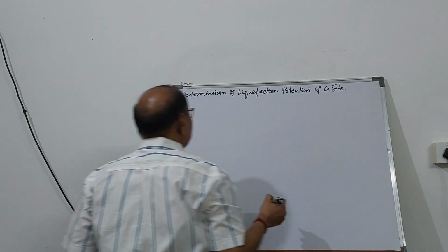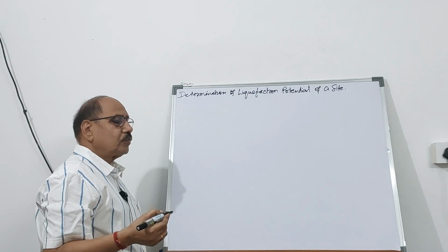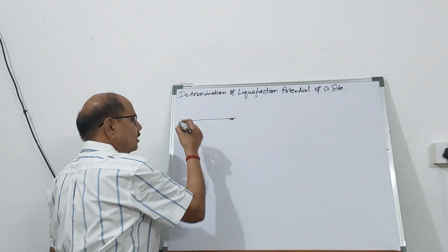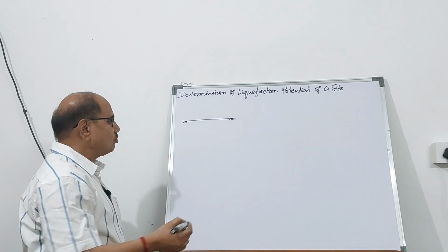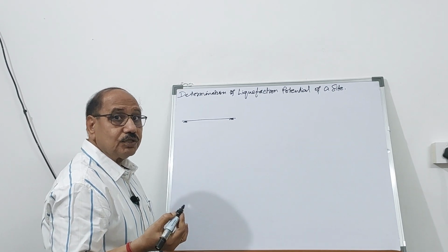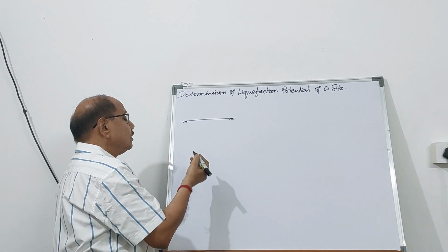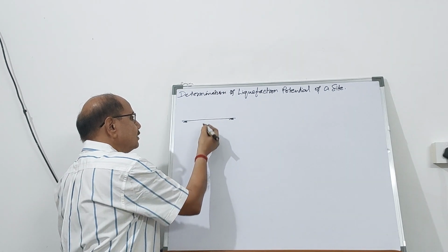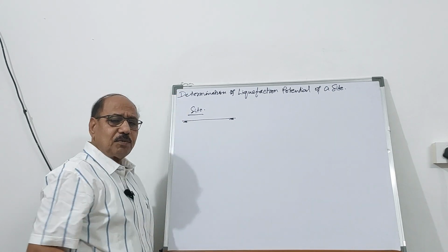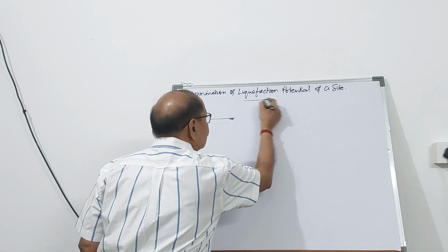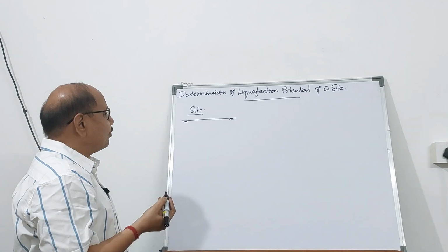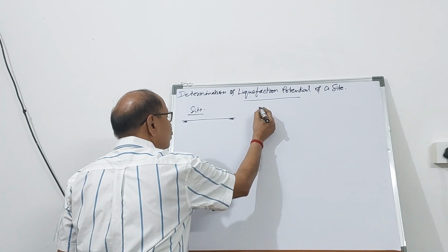is now mandatory in India. So before construction, when you go to a site, you need to find out whether this ground will liquefy when the earthquake is going to strike. So during the earthquake, this particular site, before construction takes place, you must find out the liquefaction potential. And the various field tests that you can do are known to you.